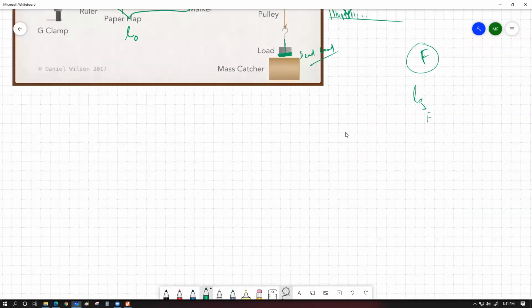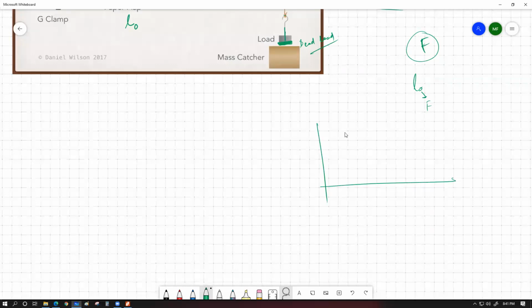So this is the part that I wanted to understand. Let's say for a true wire, the force versus extension graph is like this. Whenever we apply the dead load, let's say of this much, then let's say it does this amount of extension. So this is becoming this point. We can very well choose to start our graph from this point. Our force and extension graph can also start from this point, and this is not going to give us any different graph than the earlier case. The gradient that we're going to have for starting from this point and the gradient we're going to have starting from this point are going to be exactly same. Don't you think?